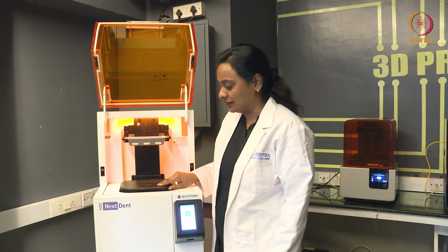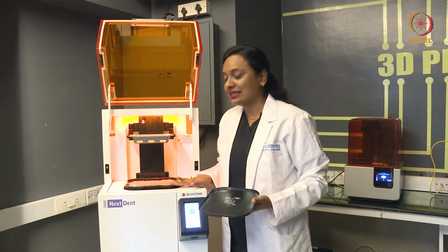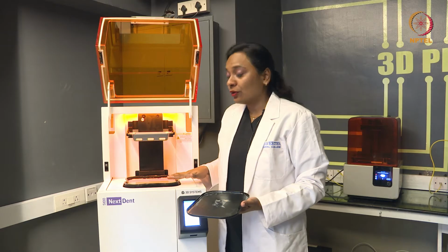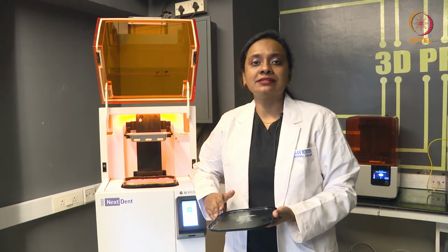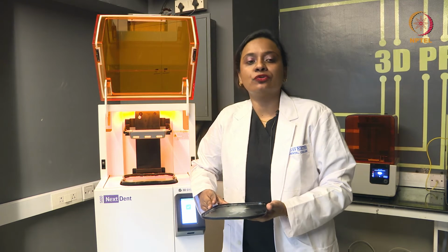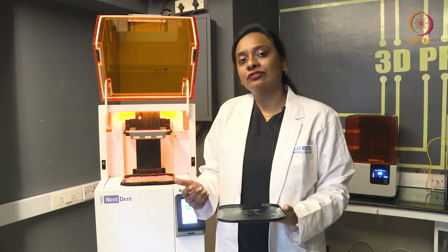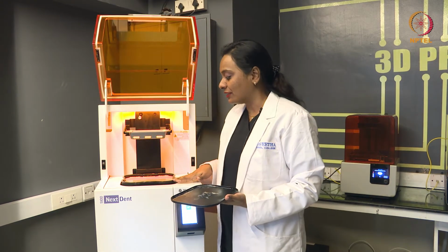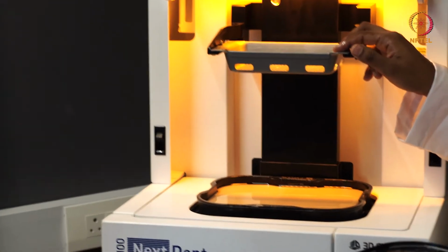Next, you have the resin. So this is the photopolymerizing resin. You can see that this is a resin tank in which the resins are stored. So there are different resins. For example, model resin, which is used for laboratory purposes, surgical resins, which are used for printing of body parts. Then we also have flexible resins, in which we can print flexible structures. So we have a lot of other resins also available for printing. Before starting, we should ensure that the resin tank is full with resin and the printing bed is clean.